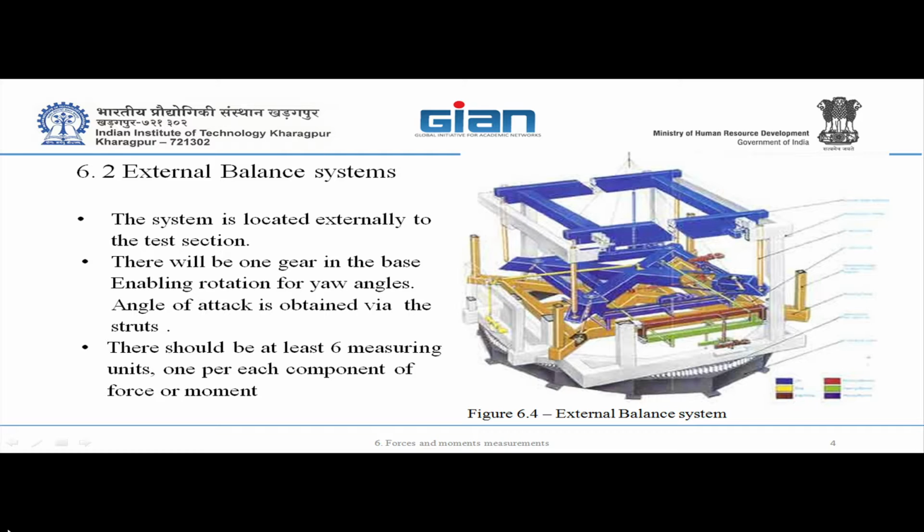Today I believe everybody will go for the strain gauges, because then there is no movement, no need to worry, and the most important thing is accuracy and frequency response, because you can imagine this way of balancing is very slow. You can measure only average forces and moments. The moment you want to measure dynamic, you have to move to strain gauges.